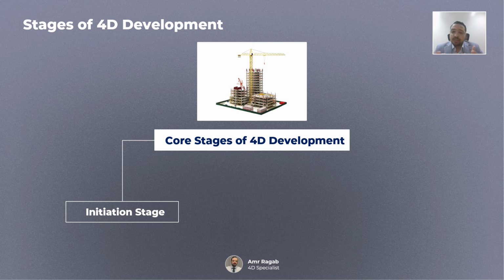So you need to split it into parts, otherwise it will cause many problems in the next stage when you convert these parameters to the construction model. We need to discover all these issues and tell the BIM team to edit them before the linking stage. This is the first point.